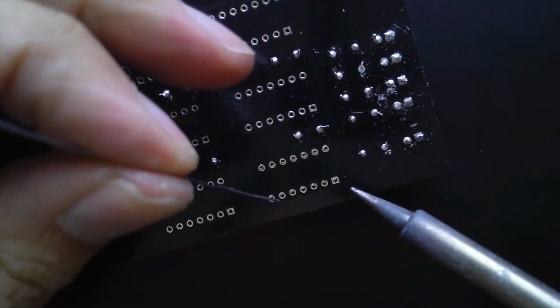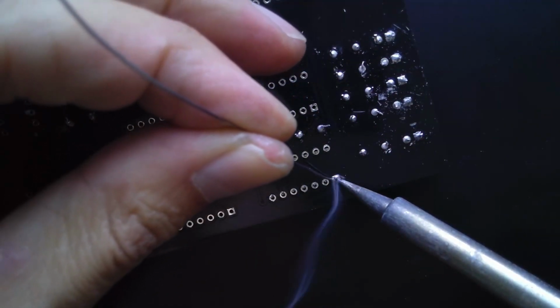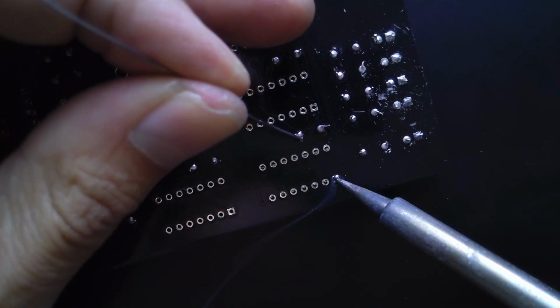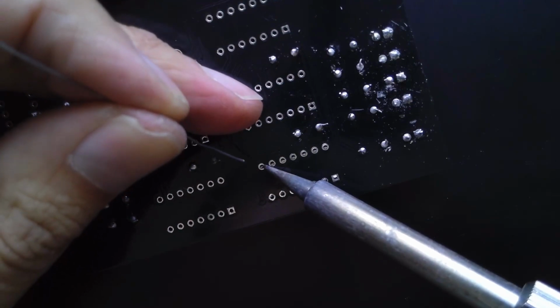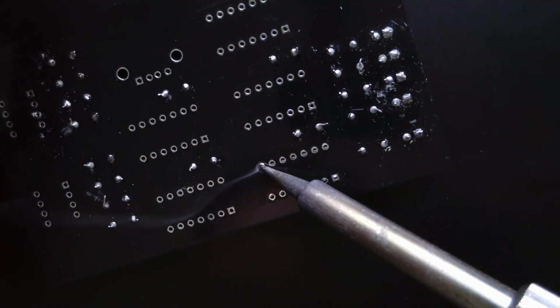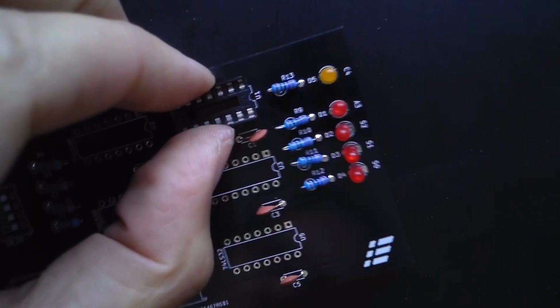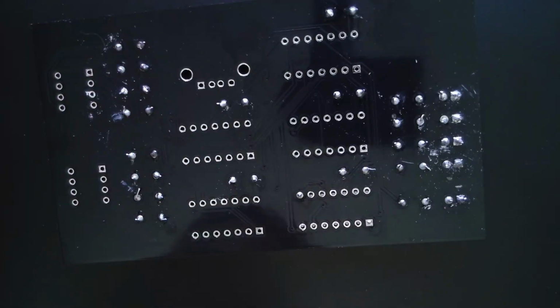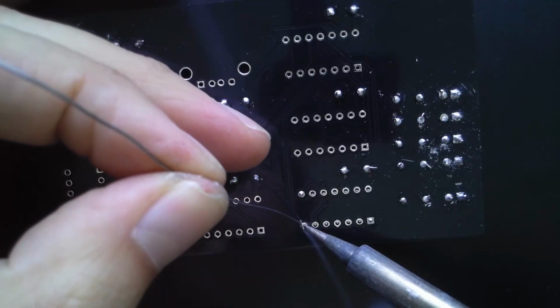And when we're soldering larger components like this integrated circuit socket, it's a good idea to solder one pin on the corner, pushing down nice and hard, and then the other pin on the diagonally opposite corner, pushing down again fairly firmly. That locks it into place, and now that socket is nice and secure, and we know it's going to be in place properly. Then we can go ahead and solder up the rest of the pins.